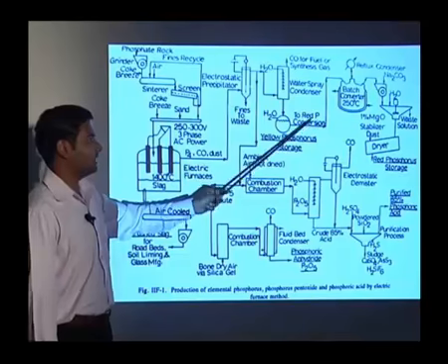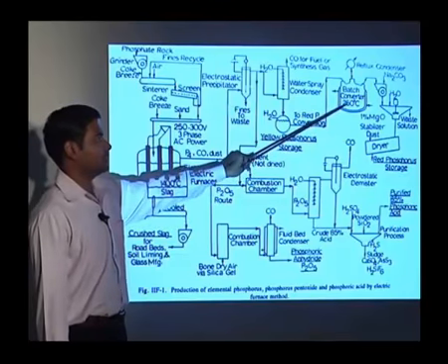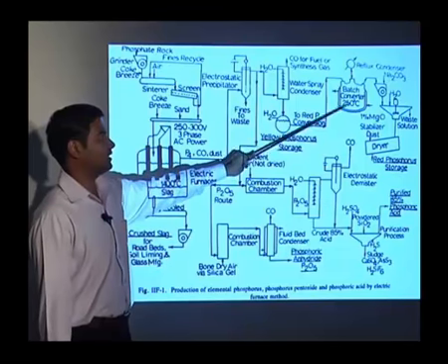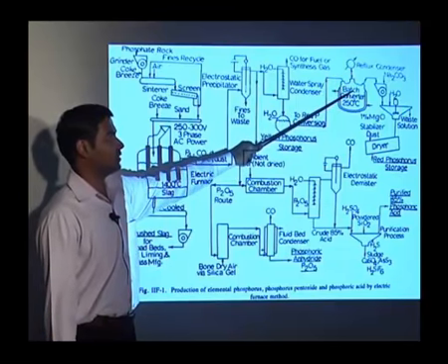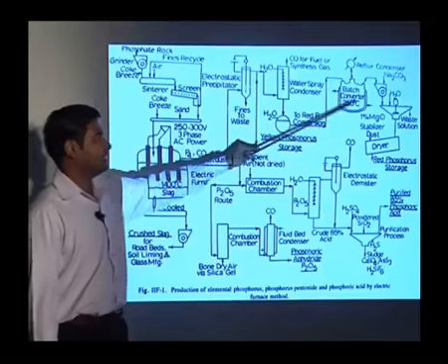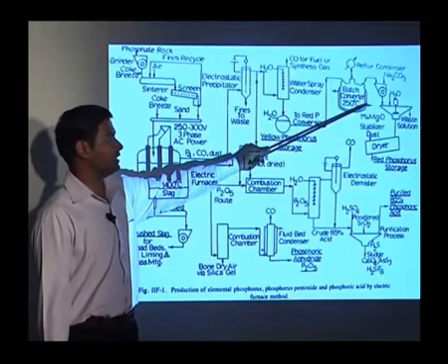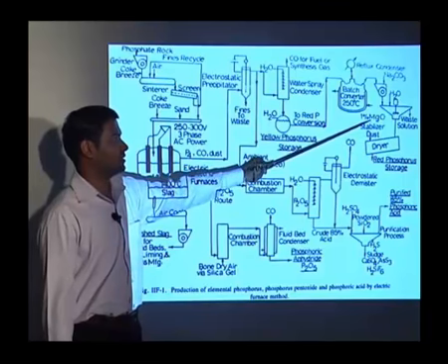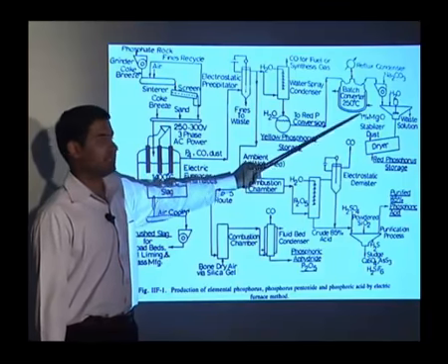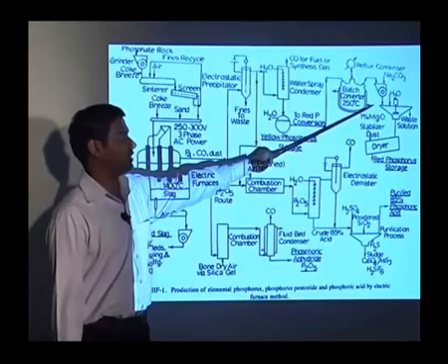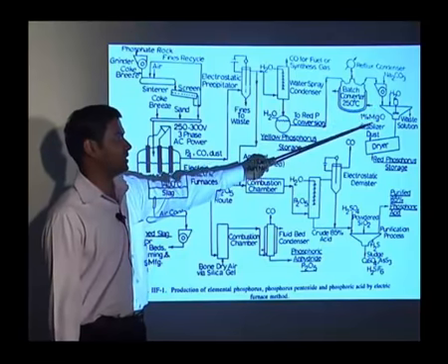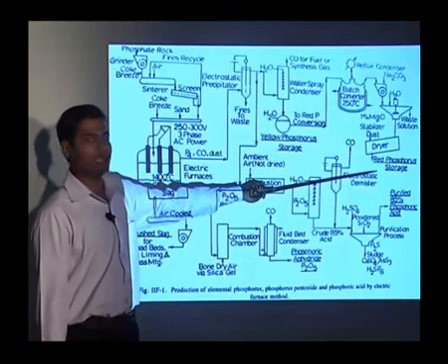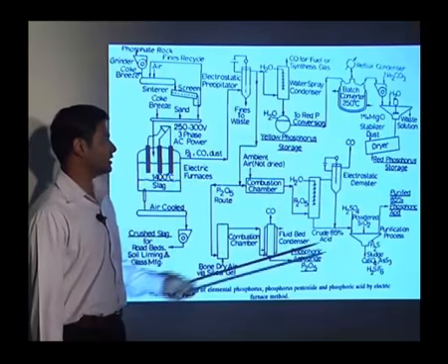For the red phosphorus conversion, we keep it in a batch converter. The reaction temperature is 250 degrees centigrade. We can have the reflux condenser over here. Then we add Na2CO3 into it and 1% of magnesium oxide to get it stabilized. So Na2CO3 is required and 1% Mg is required to get it stabilized. Then we can dry it and send the red phosphorus for storage.